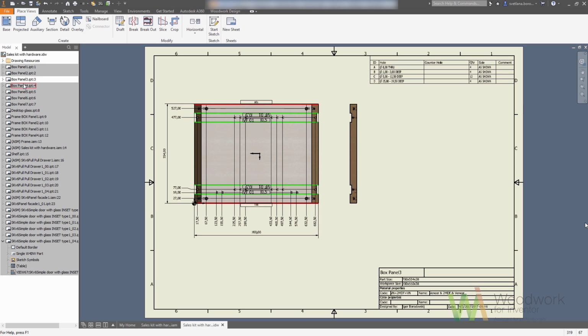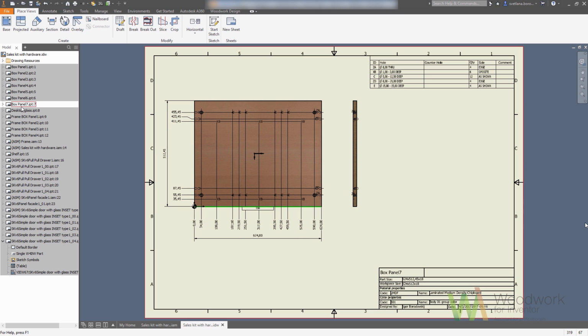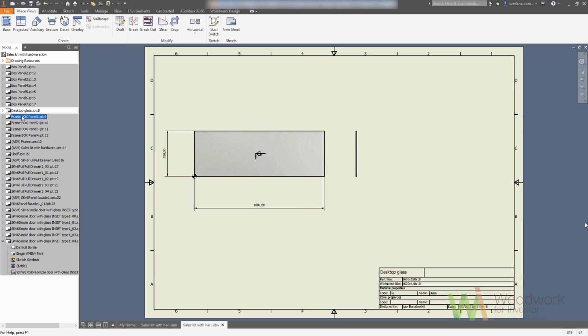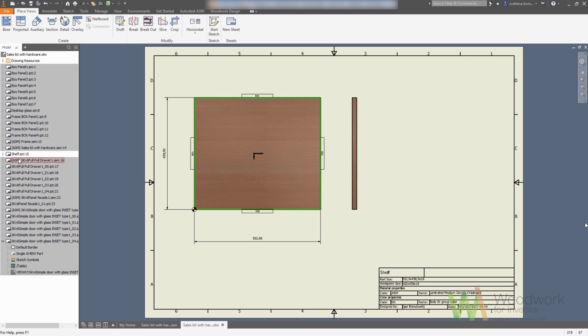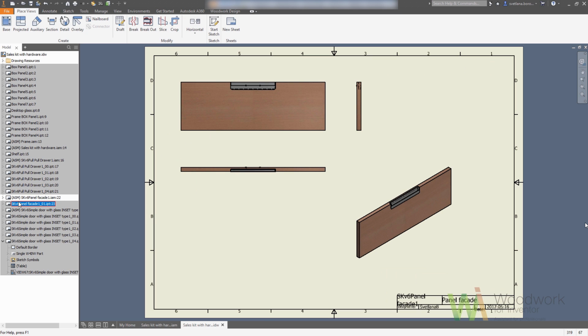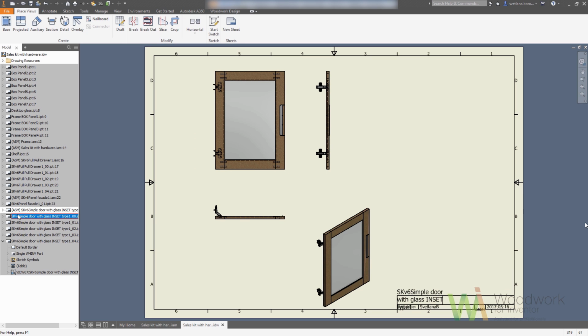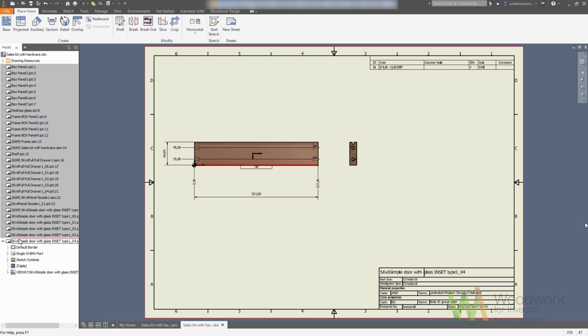As you can see, each part is oriented in such a way that as many holes as possible are on the top. We get the coordinates for the holes, we get the hole chart on the top of the drawing, but it's a matter of adjustments. If you like, you can change the position, move it to another side, and so on. We get the grain direction, we get the edge banding, the color represents different thicknesses, and in this way the template shows the main assembly, and then it goes through the subcomponents, and it repeats this again and again till it reaches the end of the assembly.